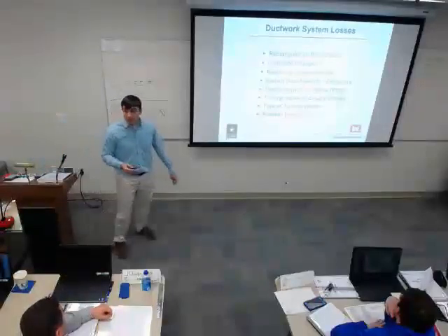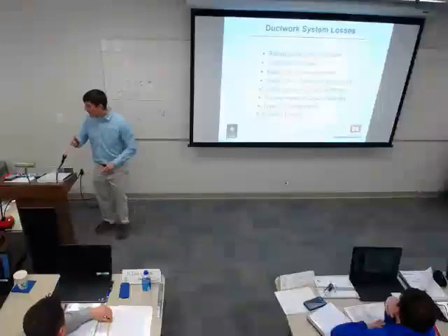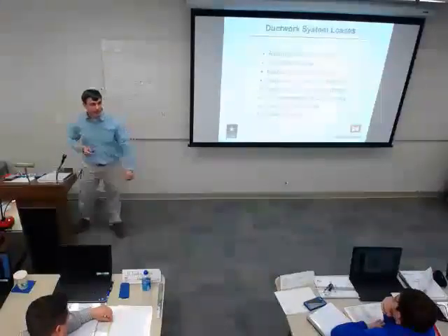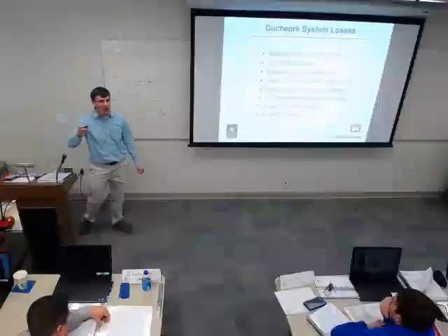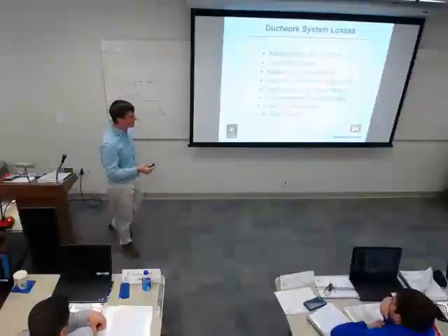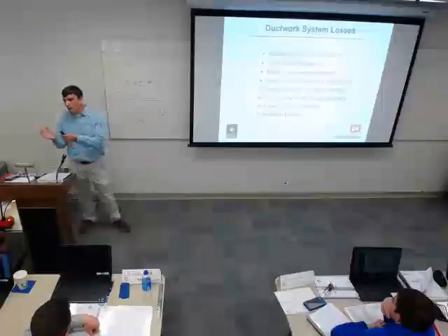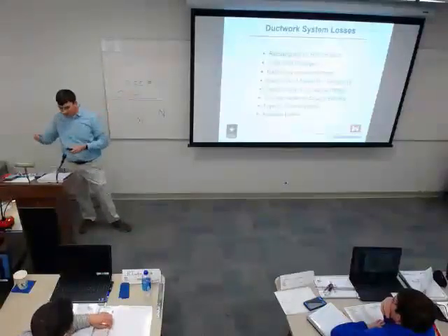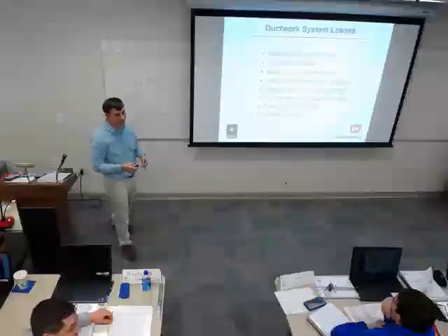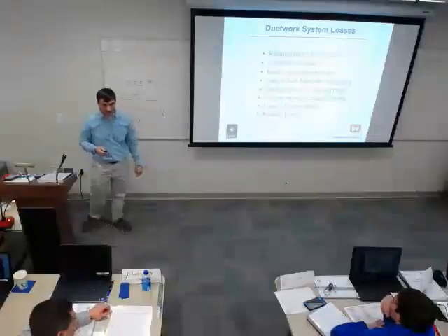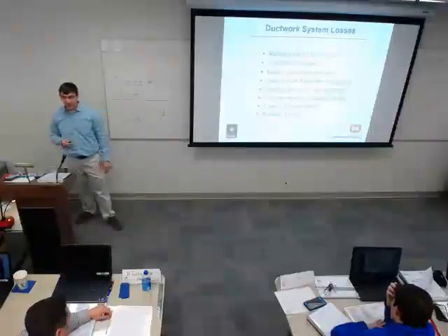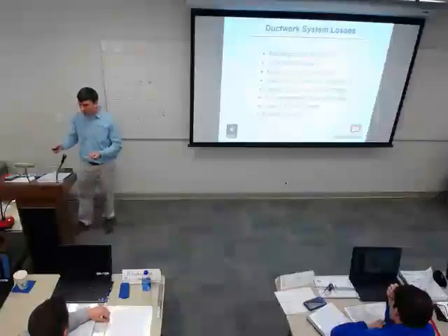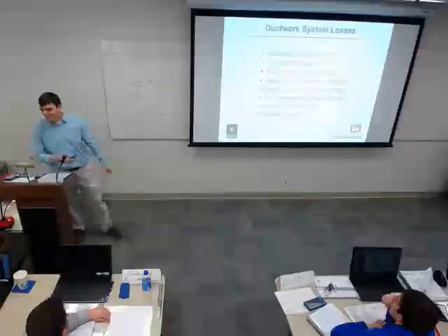What are extractors? I'll find you an image of it. I had to look it up. It's basically a little scoop that goes into the ductwork to try to bring the air down. It's adjustable. Some of them are like turning vanes and swing into the duct. No matter what they are, you don't want them. One of these TAB standards, as I was reading for the class, actually says these things suck.